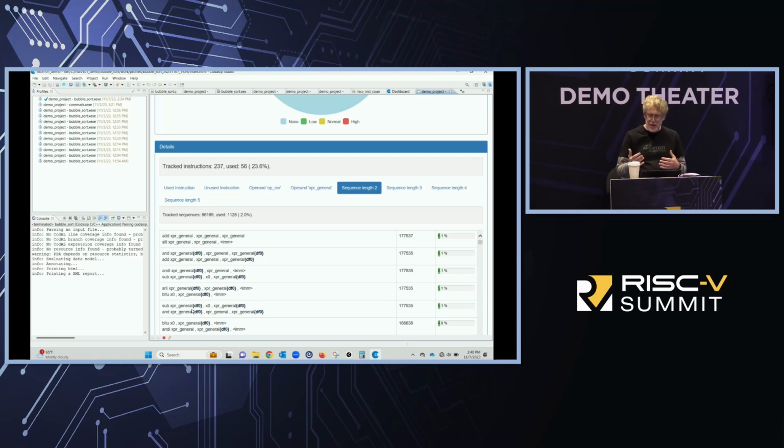And the next instruction, what I'm doing is ANDing it with a different register and then storing it back into the original register. So it's sort of like a mask type of operation. It might be tough to see, but on the far right of that, it happens like 5.1% of all instructions. So if I can collapse those two into one, I should save about 5.1% of cycles, right? Because now 5.1% of the time, instead of 2 instructions, I'm going to do 1. It might not be exactly the same because now the compiler might start rearranging the code somewhat.